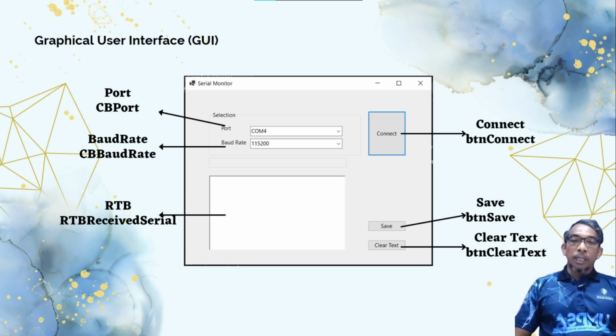And then the rich text box. This is where the data received from the Arduino is displayed in real time. It continuously updates as the Arduino sends data through the serial port. And then we have a combo box, in which we have baud rate and COM port. For baud rate, this is a drop-down box where the user can select the baud rate.